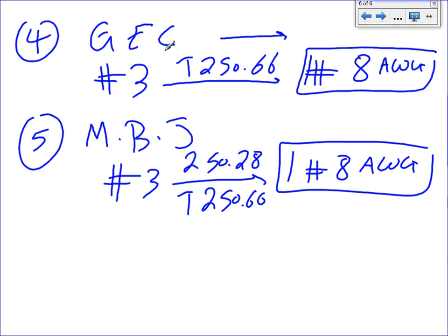But we're strictly looking at the welding loads only. When we go to the commercial building, guys, we're going to have process loads. There are machines sitting on a manufacturing floor doing things, making things. You add them like welders, not the same calculation, but lump sum them in a certain way and add the lights, the HVAC equipment, and the receptacles to size them in. I hope you're getting into the rhythm of doing it.